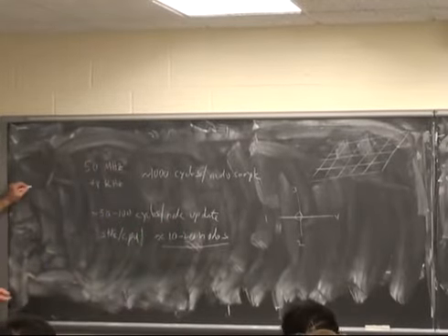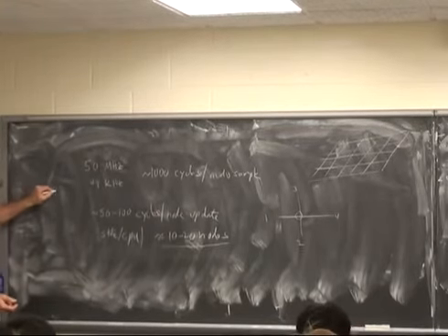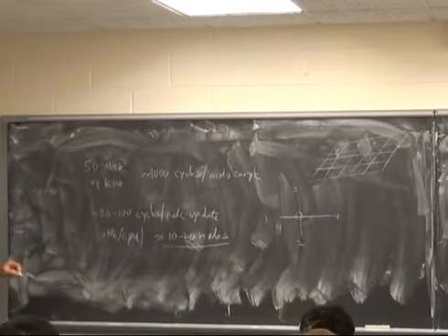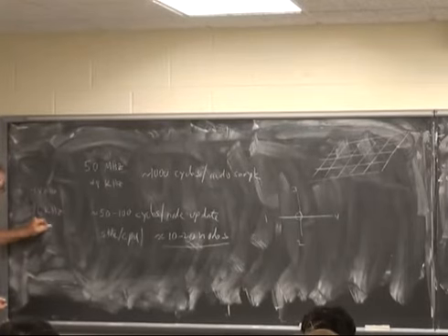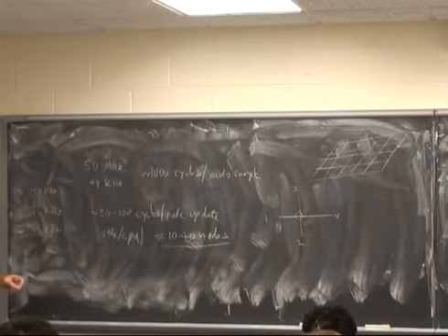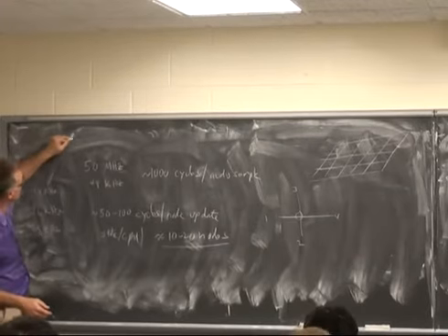Oh yes, I should say also, the default rate for the audio codec as written is around 48 kilohertz. I think it's actually 47. You can double that to 96 kilohertz if you want, or lower it as low as 8 kilohertz if you want more time to do samples, because what you're being graded on is the product of sample rate fs times number of nodes.